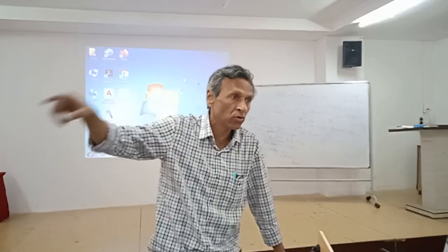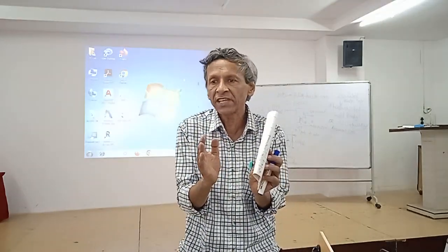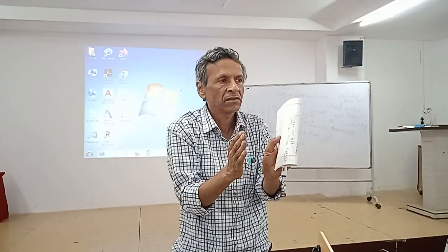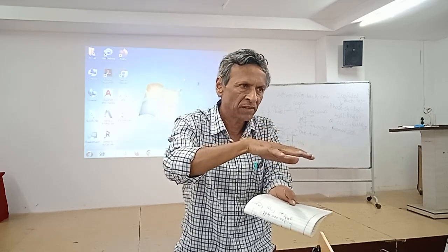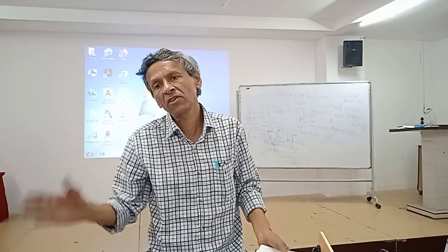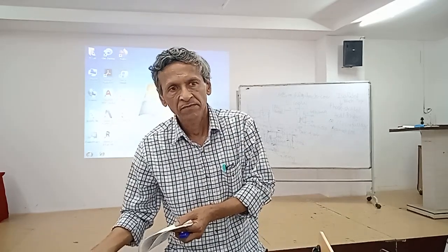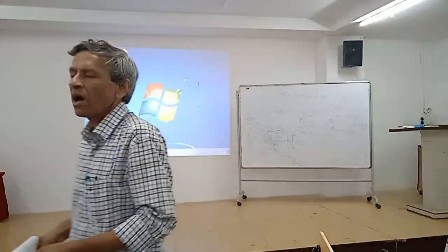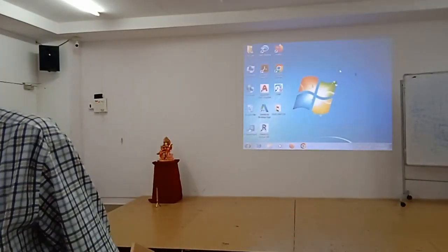So from 50 hertz, you have gone to 15 kilohertz. So many times. So suddenly your 10 kVA or 10 kilowatt transformer will be of this size, practically only this size. You have to manage cooling, that's all. Force cooling, that's all. And suddenly it can transfer power of 10 kW. And then you can take the advantage of turn ratio and then get the feedback, and you will have a very good supply. And let me tell you, suppose I develop this supply, in fact, we are developing a 3 kilowatt supply of this type.